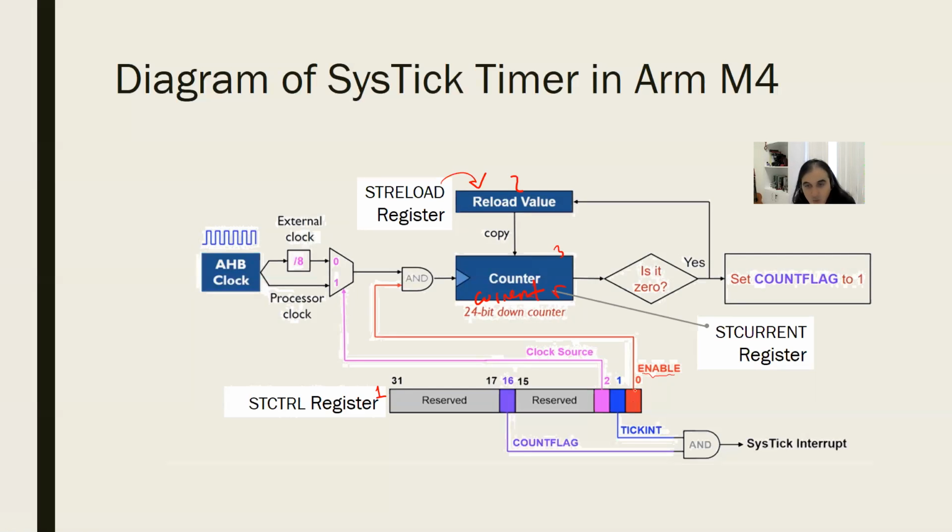If this bit is 1, this wire is 3.3 volts because logical 1 in our system is 3.3 volts. It is connected to this AND gate, guys. As you can see, can you follow the red cable connected to enable? And the other pin of the AND gate is connected to a clock. Which clock? I don't care. This is the clock. So clock is coming in, guys.